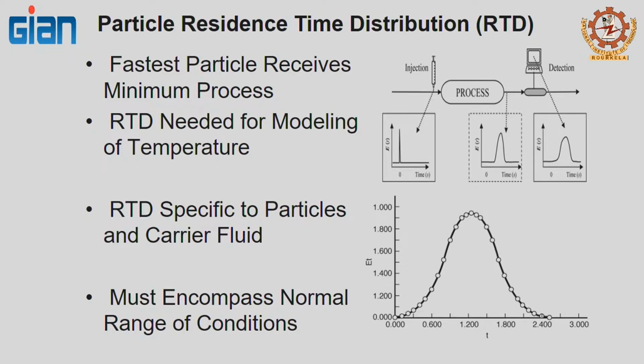So, here we are getting into a little bit of food engineering or chemical engineering concept, the residence time distribution. Basically, the concept is, say you inject 100 particles, you are passing them through a holding tube, and then you are going to measure how many particles come through. Ideally, all the particles would come at the same time, but this is almost not practical. This is more practical.